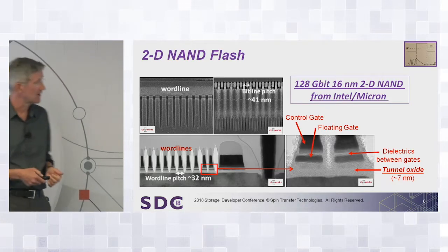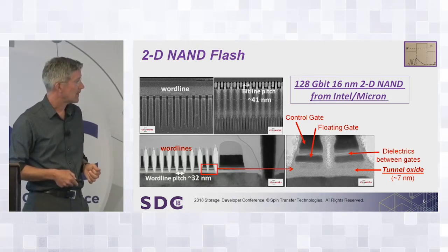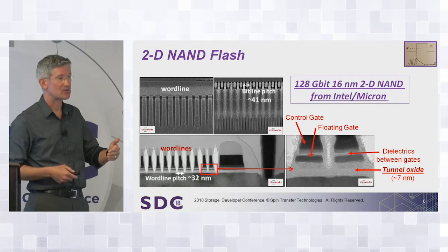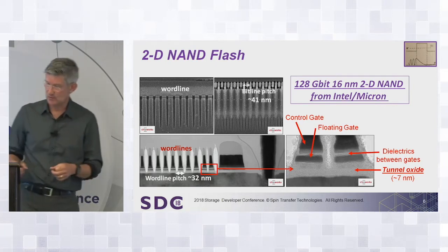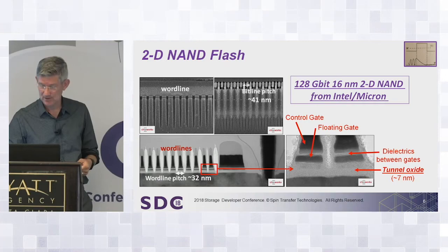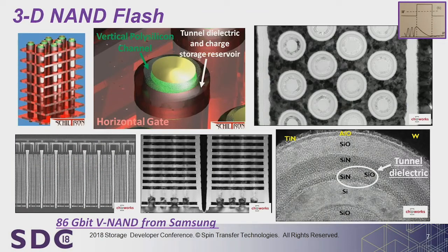And as we all know, that is having problems in scaling below half pitch of about 15 nanometers. So the manufacturers saw this coming, so they started working on the 3D versions. But again, 3D versions have the same three mechanisms, structures involved, the foundations. Here's 3D NAND. Looks complicated, but again, here's some beautiful work from Chipworks, Tech Insights, cross sections. You can see the strings going up and down. It turns out to be the contact to the source at the other side. It's an amazing technology when you look at it.